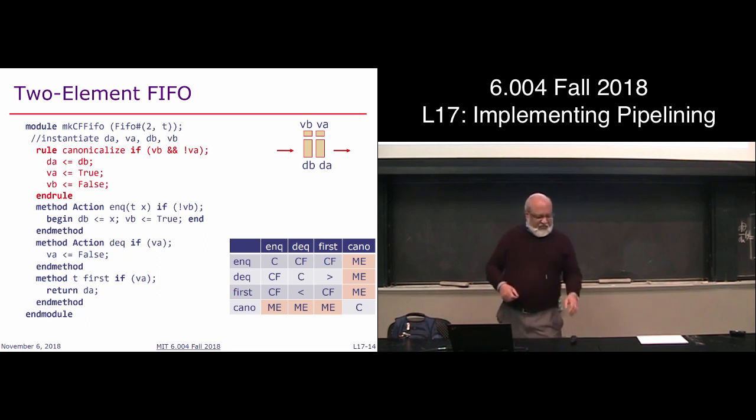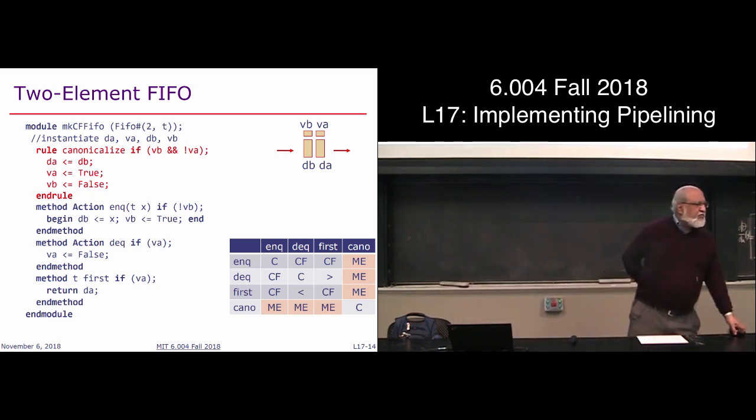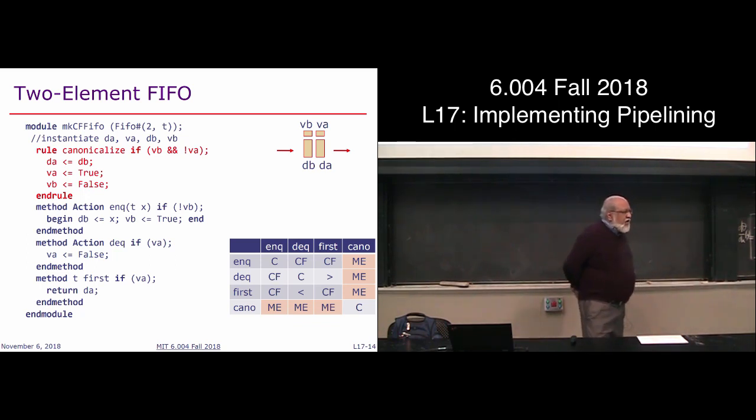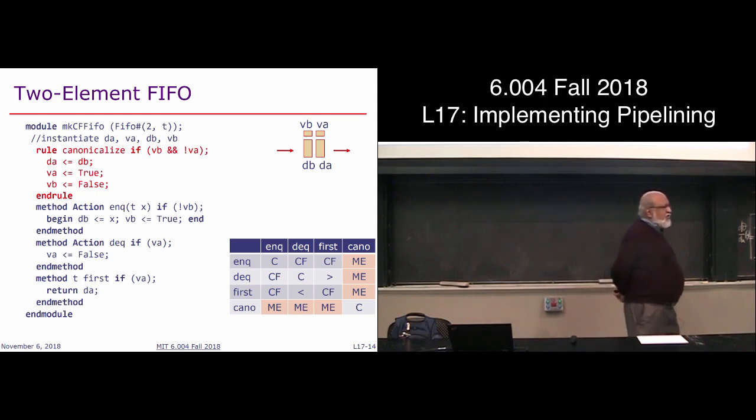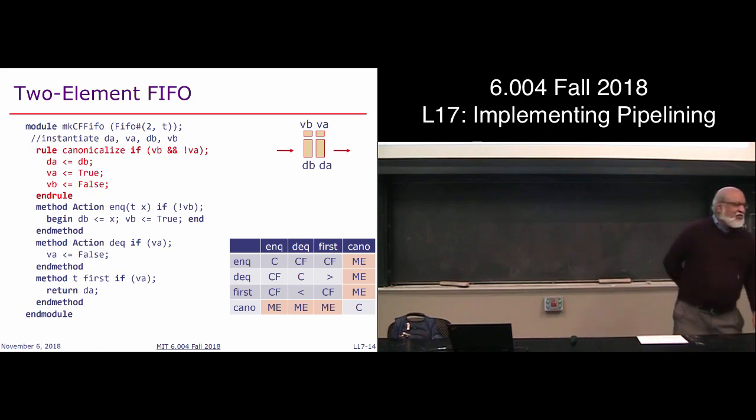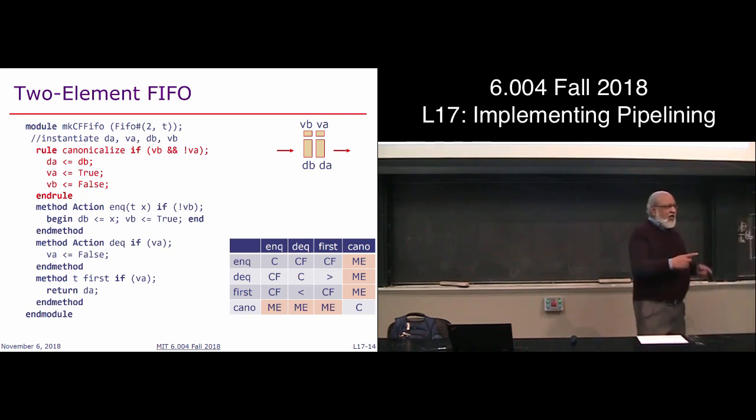Okay, so we have 3 different kinds of methods in Bluespec so far: action, action value, and value. Is it true that for all non-value methods, so action and action value, we will have a conflict with itself? It's self-conflict, right? But with value methods, it'll always be conflict-free. Actually, I would like it to be true, but that's not true. Why can there be a conflict? Because suppose you were trying to read two things together in a register file.